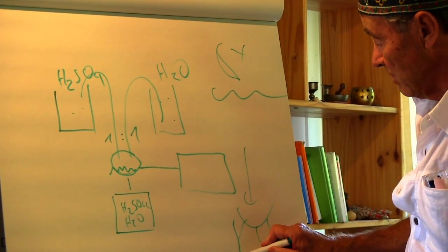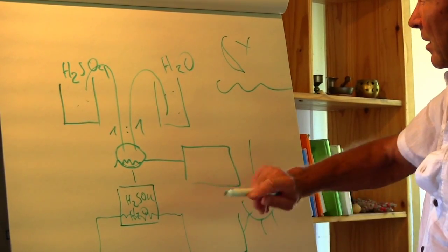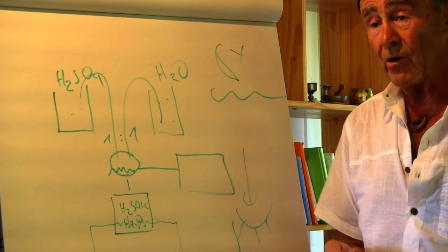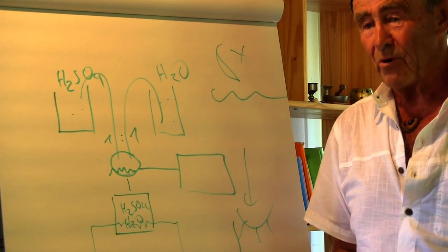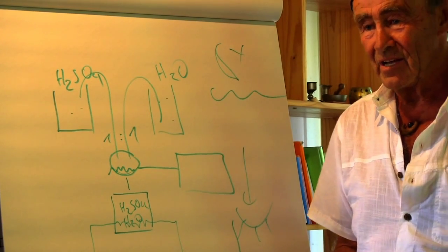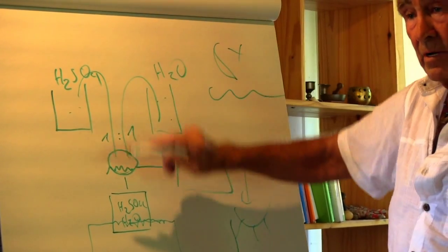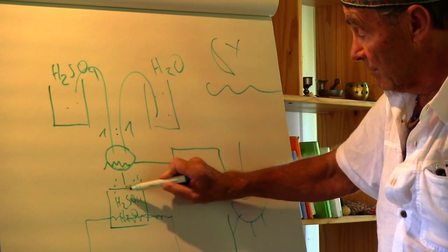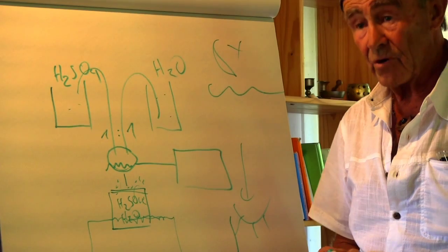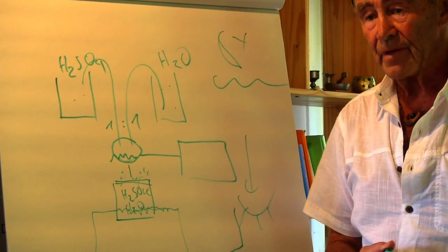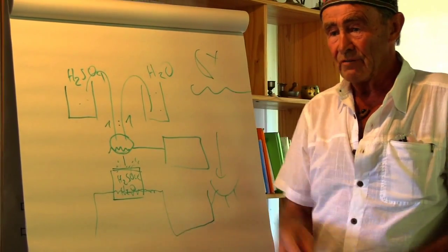But now you put a heat exchanger inside, and as you know, H2O has a boiling point at atmospheric pressure of 100 degrees, whilst H2SO4 has a boiling point over 200 degrees. So solar heat out of our collector system boils out the water. We take care that there is no acid coming dynamically out. We did this, so I'm not speaking theory, we have done this. We take an active carbon shield through which the water vapor goes.